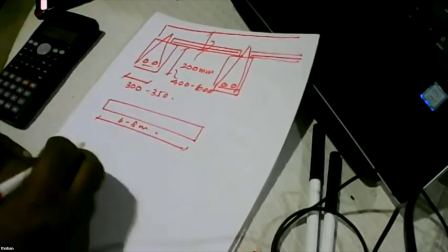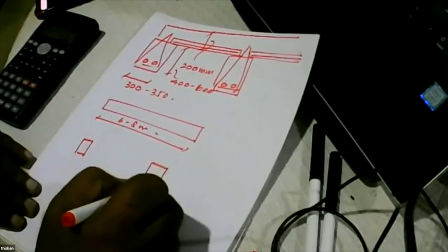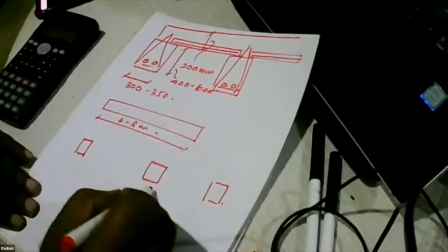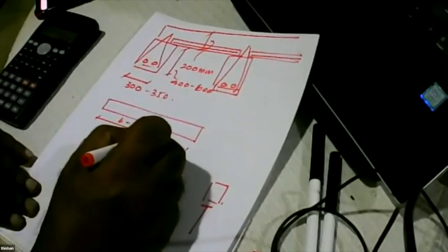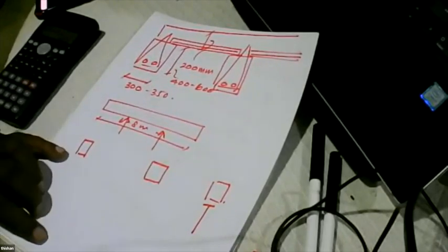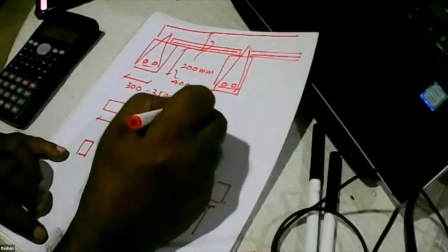And then we lift it up and place it on the supports. Supports are abutments and piers. If you like, you can give a prop as well at 2 points. Sometimes giving a prop is not that feasible. Generally, when you are giving a prop, we give the prop at 1/3 point.